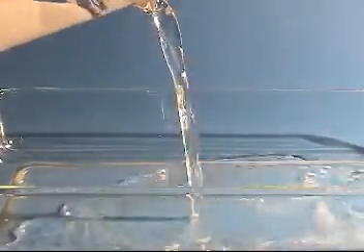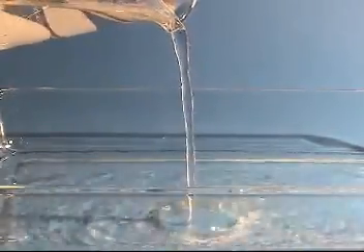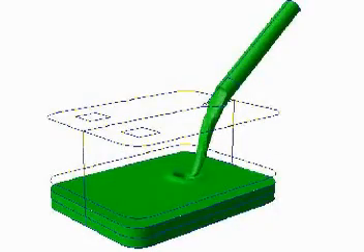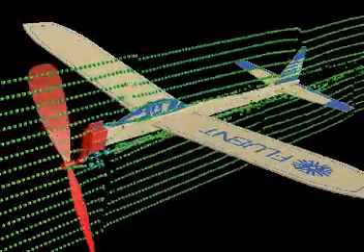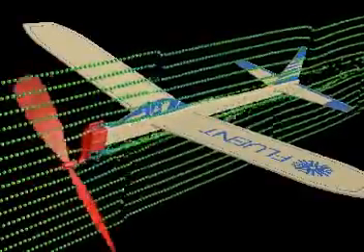Next, we classify flows as incompressible or compressible. Most liquid flows are incompressible. Thus, we keep the fluid density constant when we solve the equations of motion. Gas flows are also incompressible at speeds much less than the speed of sound, as in the airflow around a toy airplane, or around a spinning football.